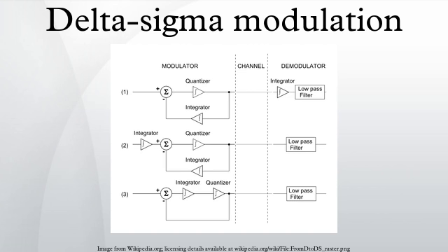Firstly, for impulses generated immediately the threshold is crossed as previously discussed, and secondly for impulses delayed by the clock. The effect of the delay is firstly that the ramp continues until the onset of the impulse, secondly that the impulse produces a fixed amplitude step so that the integral retains the excess it acquired during the impulse delay, and so the ramp restarts from a higher point and is now on the same locus as the unclocked integral.